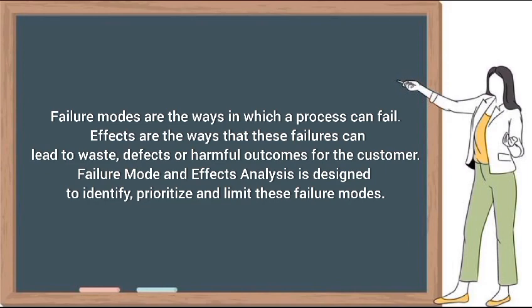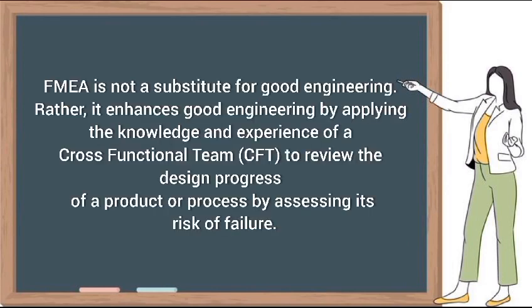Failure modes are the ways in which a process can fail. Effects are the ways that these failures can lead to waste, defects, or harmful outcomes for the customer. Failure mode and effects analysis is designed to identify, prioritize, and limit these failure modes. FMEA is not a substitute for good engineering. Rather, it enhances good engineering by applying the knowledge and experience of a cross-functional team, CFT, to review the design progress of a product or process by assessing its risk of failure.